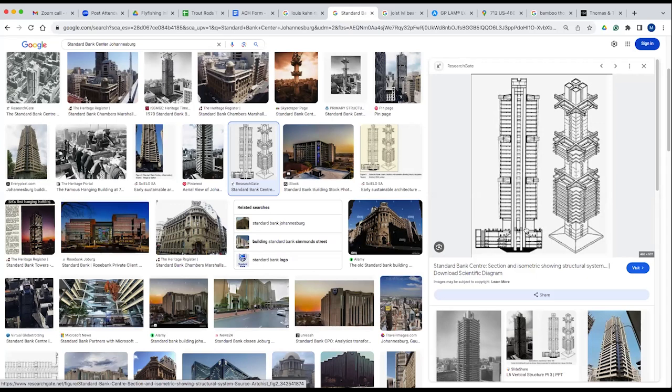How can there be concrete hangers? Because I know the hanger has to be in tension. So hangers are dropped, and the square plan is picked up by these concrete hangers that transfer the weight of 13 floors to the end of the cantilevers.